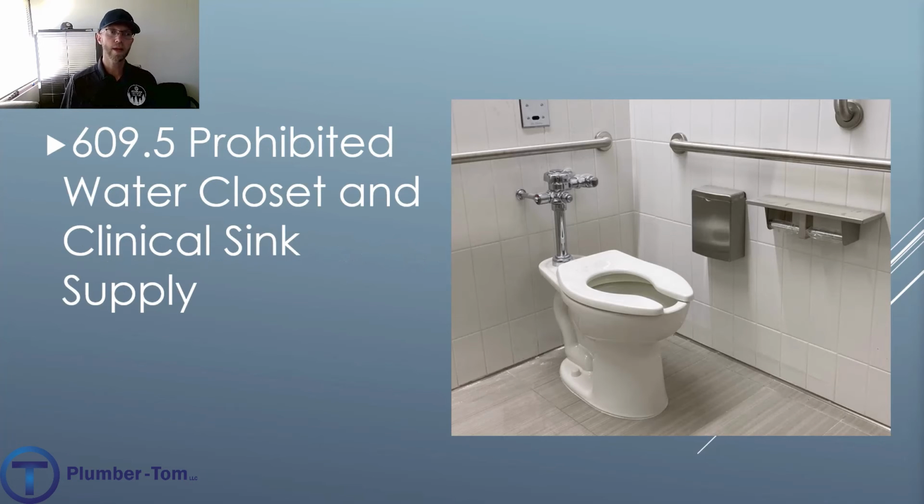609.5 talks about prohibited water closet and clinical sink supplies. Now, a clinical sink is like a water closet or a toilet. It just has a big square mouth. It's made for washing bedpans. Now, it's not uncommon for a clinical sink, or sometimes even a toilet, to have a separate faucet, like a mop sink type faucet, above that, so that you can hose out the bedpans, and then the toilet with the flush valve will flush all of that waste away.